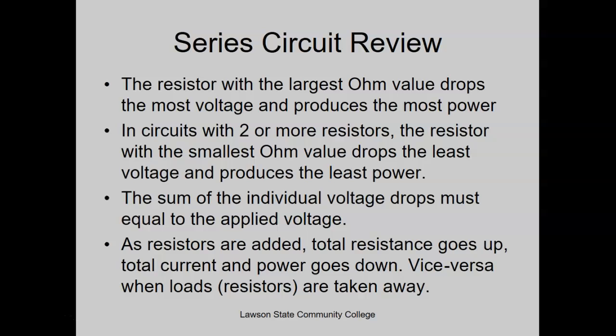As resistors are added, resistance goes up, total current and power go down, and it flips around whenever it goes the other way. You start taking resistors away, total power goes up, total current goes up.